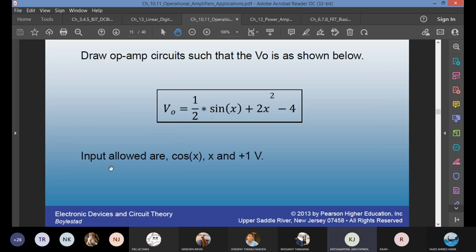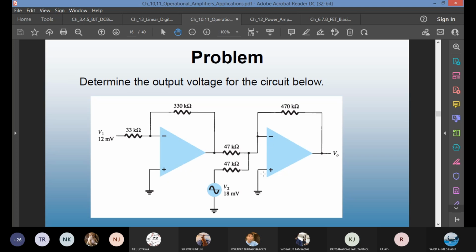I think so, I'm not sure. You have different things you're adding. Here you're just adding minus 4, plus minus 4. It should tell you this is a summing of n. And then inputs are given, the output is given. So you can see one will be a differentiator, the other one will be an integrator, and the other one will be just either inverting or non-inverting, depending on your choice of design. These are simple problems. This is an inverting summing op amp, adding two inputs.